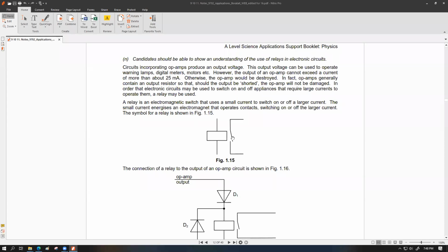This switch is usually made from soft iron material, and the solenoid is a basic coil of any material, doesn't matter. Whenever current flow does happen through this coil, it becomes magnetized, and the attraction of the solenoid causes the soft iron switch to close, and vice versa. When the current flow stops, it will not provide the connection. Now there is a catch.